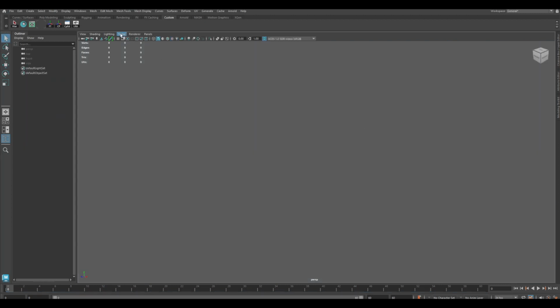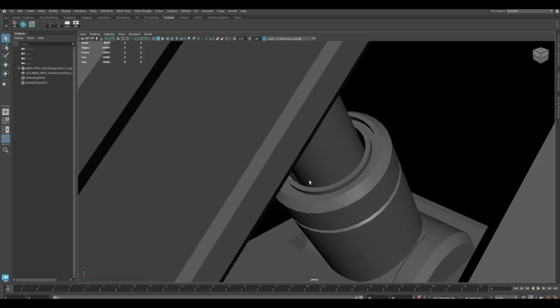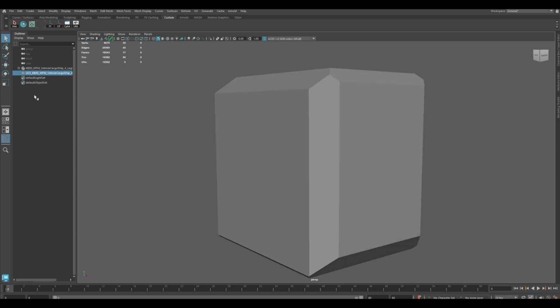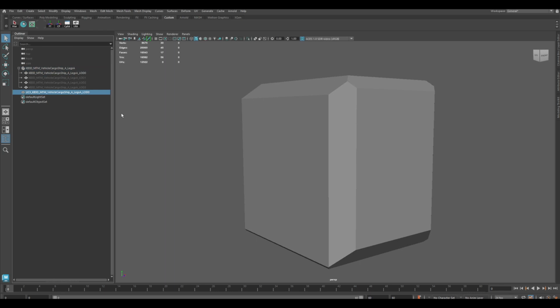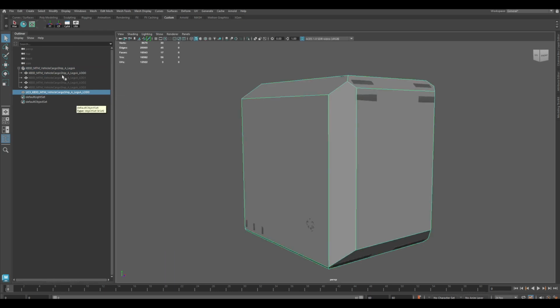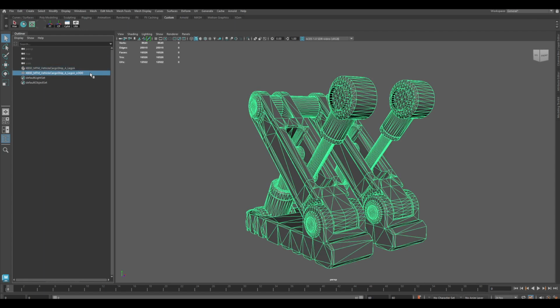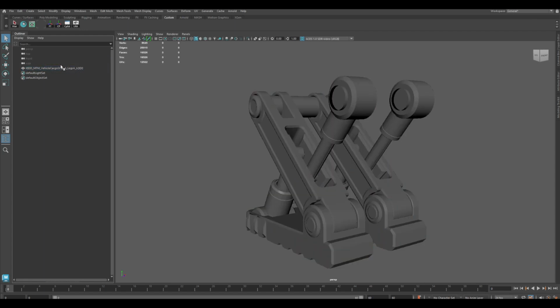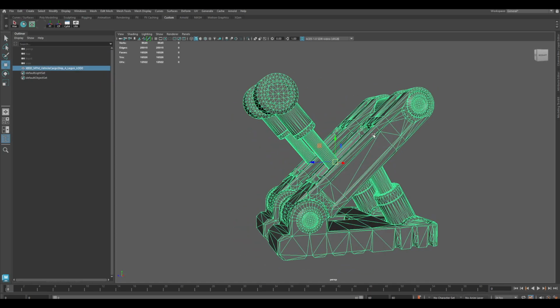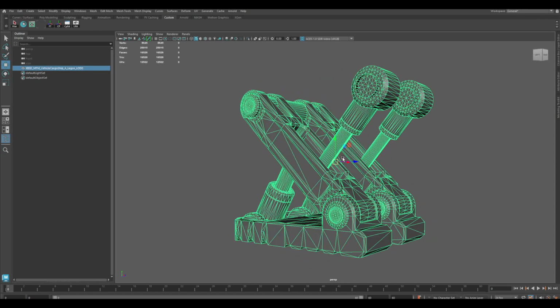and open a new scene. Import the model that you exported from Unreal. Just drag it here. It comes with 4 meshes for the 4 LOD levels and 1 additional mesh for the collision box. You don't need that for now. I'll just delete it. I'll work with the highest level mesh. I'll delete everything else. I'll unparent this and I'll delete this. I have this landing gear imported now and just single mesh to work with.